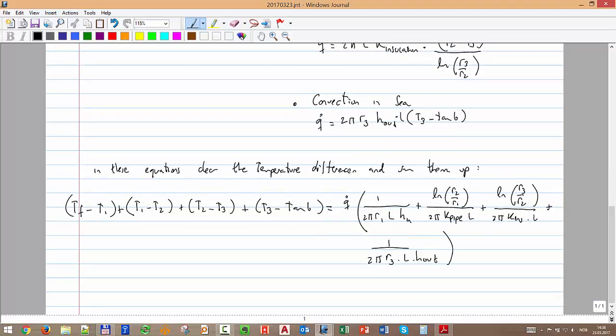So then you see that all of these factors have different signs, so all of the intermediate temperatures cancel, and at the end you get T of the fluid minus T ambient. Okay, that is the main temperature gradient. And remember, I told you it's like a difference in voltage. In the analogy to flowing pipes, what is driving the flow is the difference in pressure, in energy.